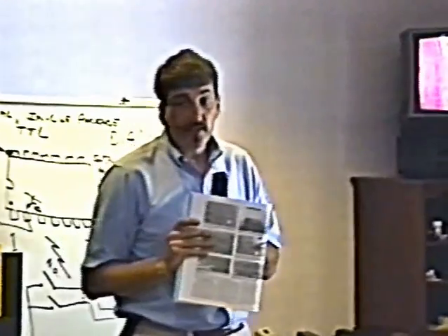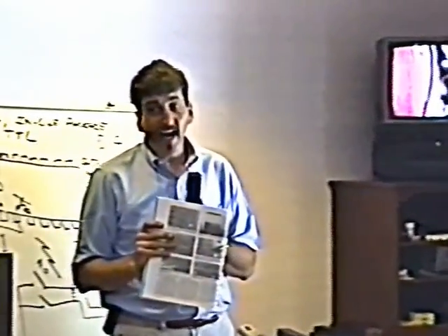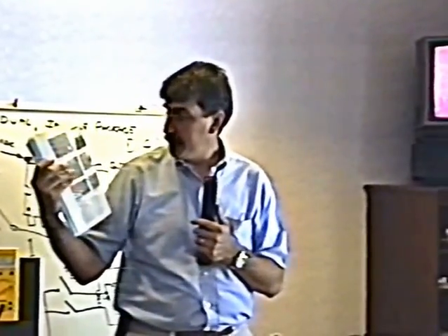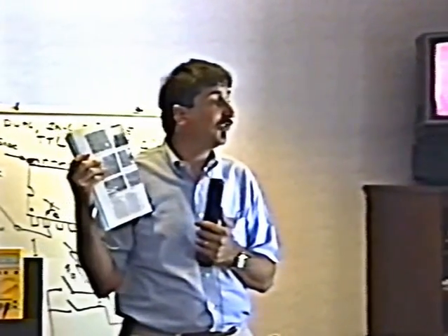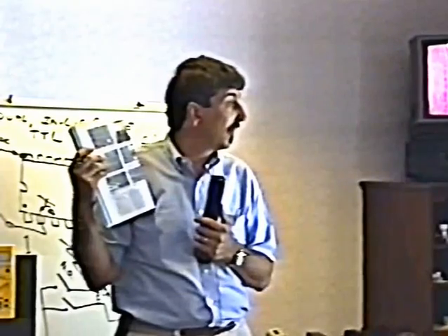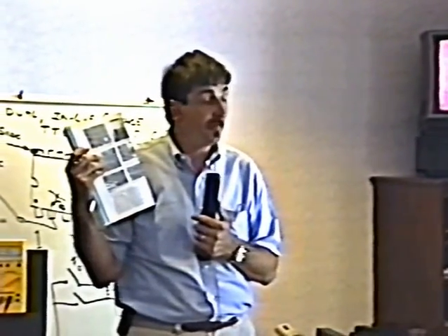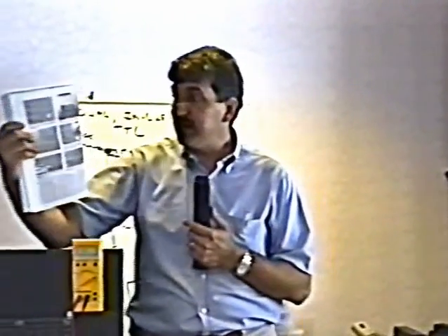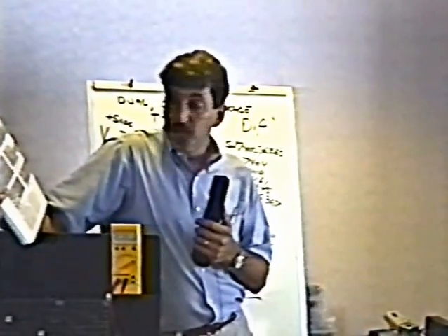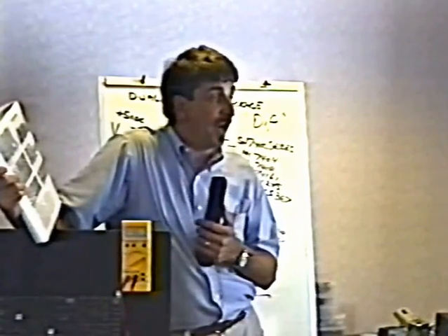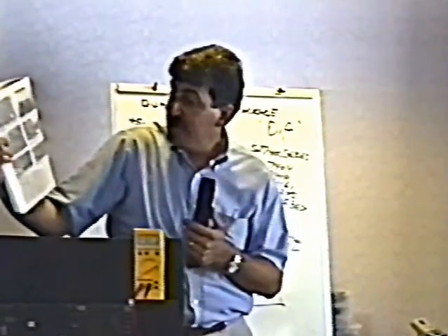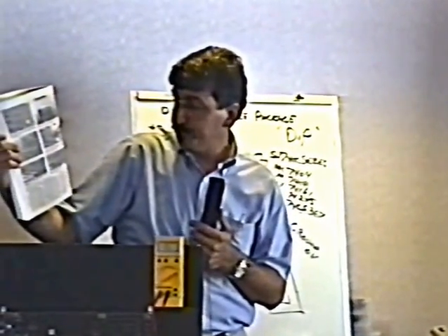To change the integrated circuit, you're actually going to cut the integrated circuit off the board. Your main criteria when you change an IC is not to damage the board. That's the important thing. You don't want to damage the board. It's really easy to damage the board. You've already determined that the IC is bad. So you cut the IC off. You cut all the legs off the IC. In other words, you cut the body of the IC off, just leaving the legs, as you see in figure 4, sticking out.